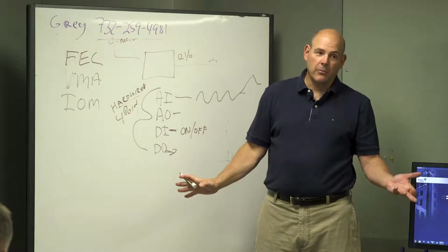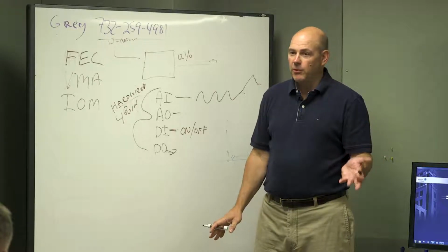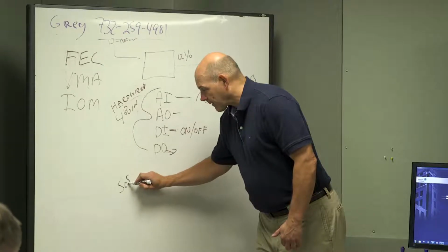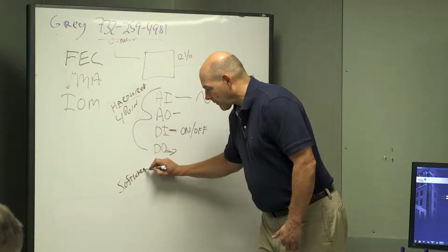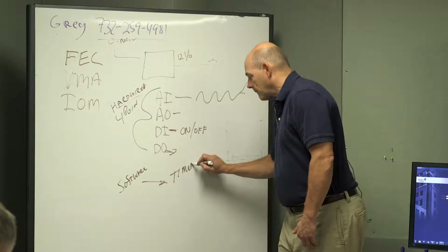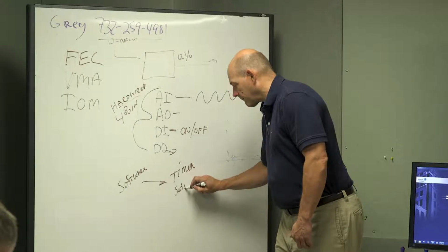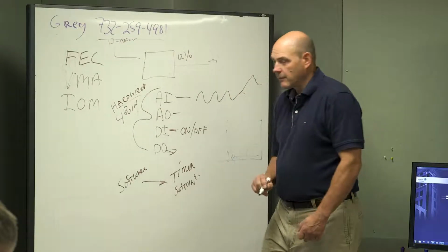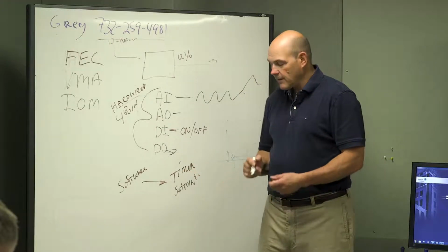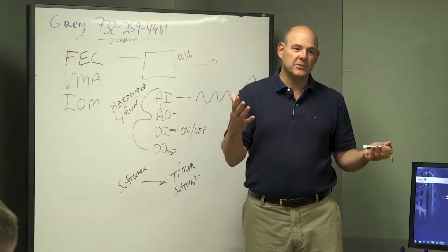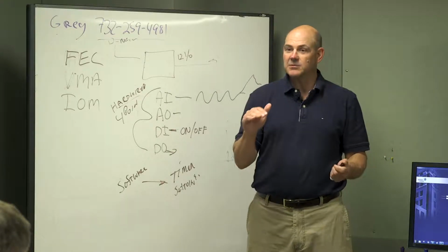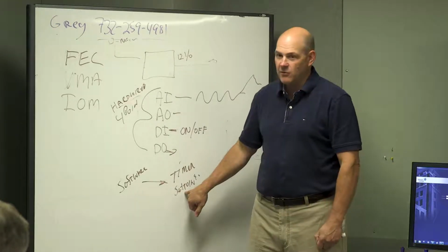Now we have software points, which are set points. Set points are software points, and timers. So in software, we have timers and set points. They're not a physical point, there's no wire to it, but it remains in software. So if you put the chilled water temperature set point at 44 degrees, there's no written rhyme or reason to it. That's what it is. It's hard-coded in the software.